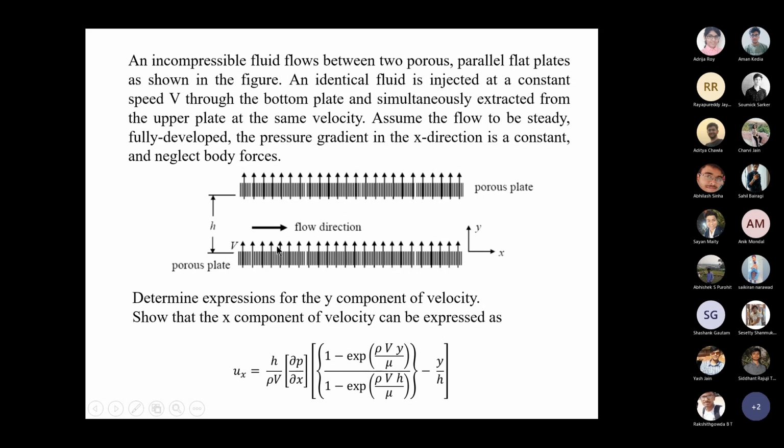When I teach you boundary layers, you would see that in some designs of shapes, this kind of suction and injection at the liquid-solid interface, the outer skin of the shape, is purposefully applied in order to disturb the formation of the boundary layer and to reduce the drag.